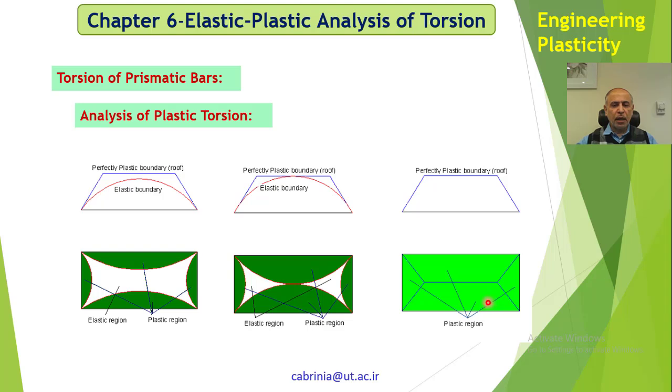Now, that idea that I presented at the beginning of this part, and said that I will explain later: why did we take K equal to the gradient of this roof? Why did we do that? In fact, we have taken this from the membrane analogy. In the membrane analogy, we know that the stress is related to the gradient of this membrane in different directions.